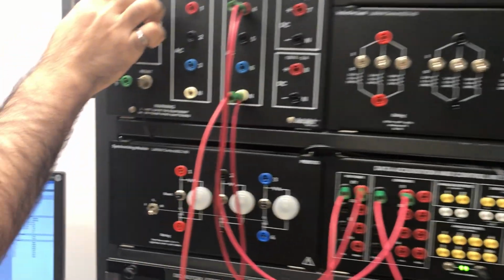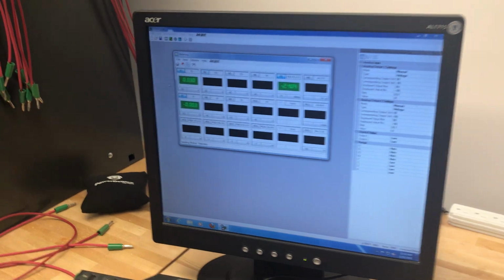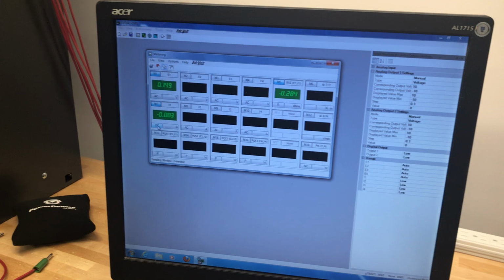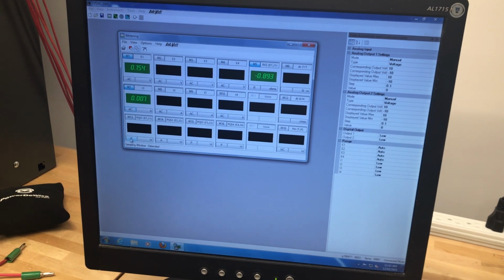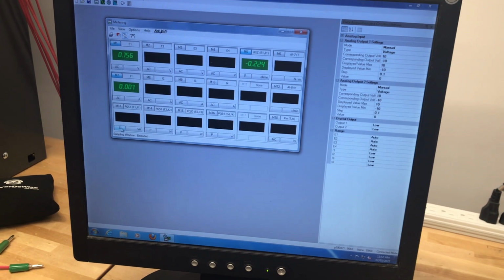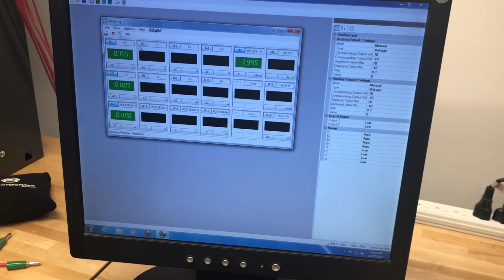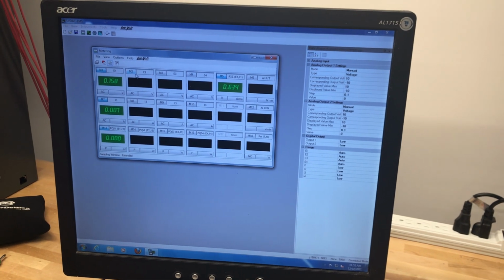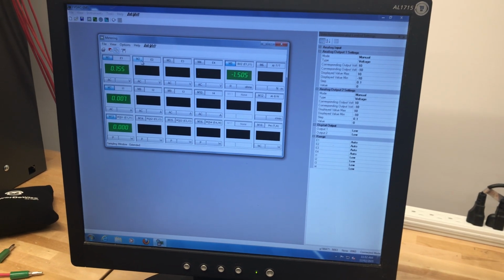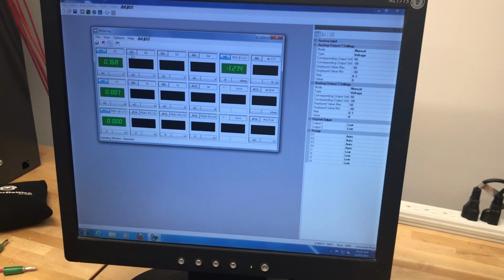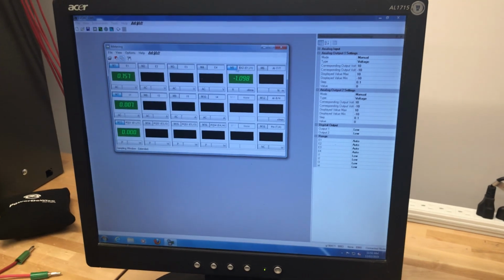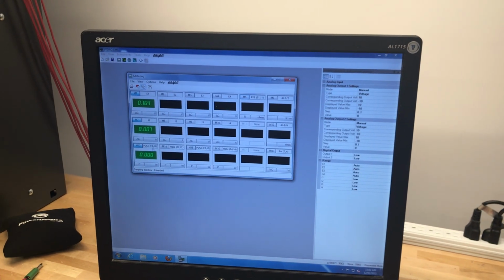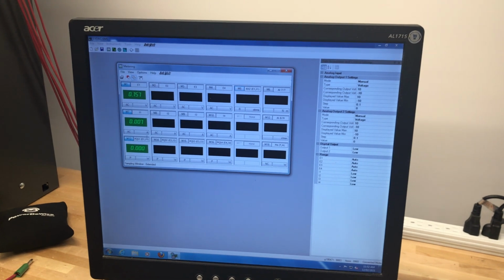So I will turn on, but before I start, I would like to measure E1 as an AC and I1 as an AC, and I would like to measure the power P as well. So this is the power P. I would like to measure the output, so I would need to connect a voltmeter for the output, but actually I don't need anything for the output. I don't need this part. I need only Vn, In, and power in. So I will turn on,